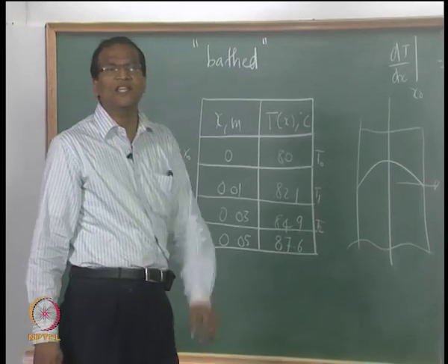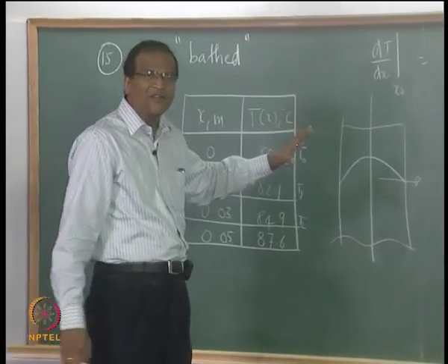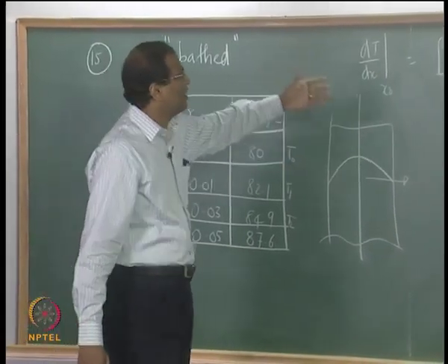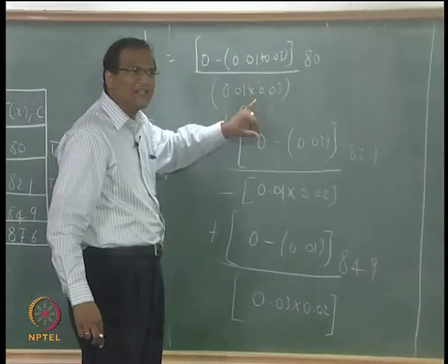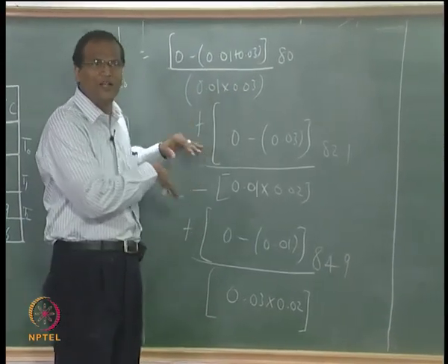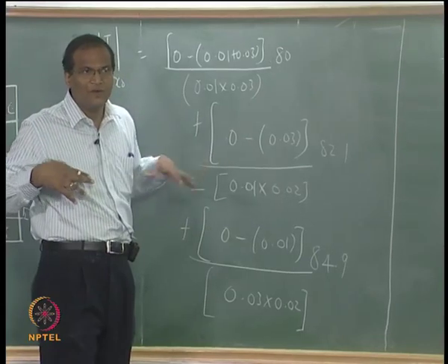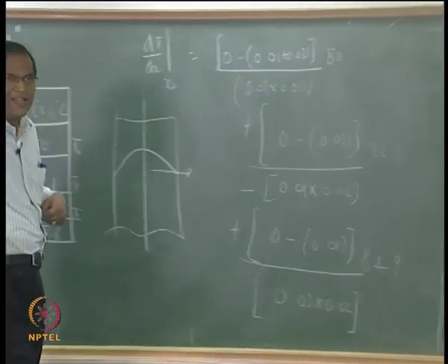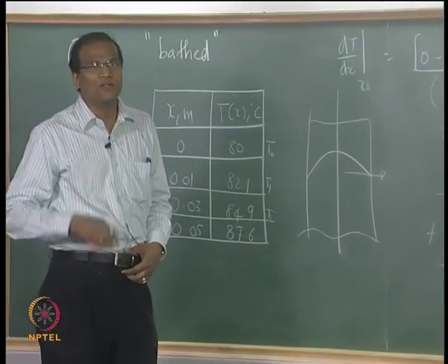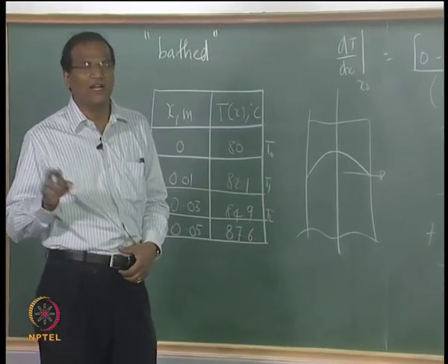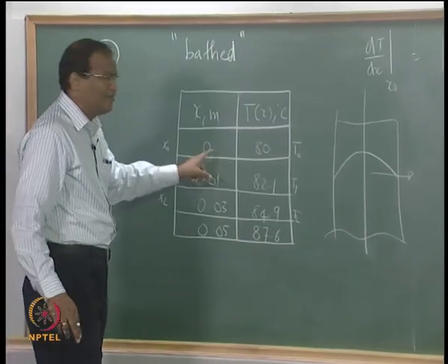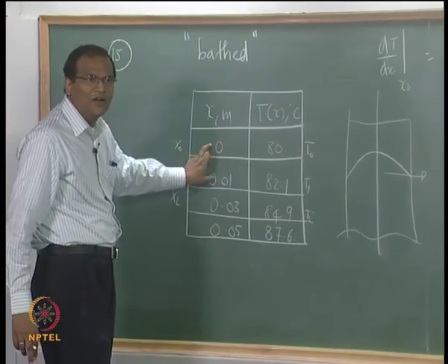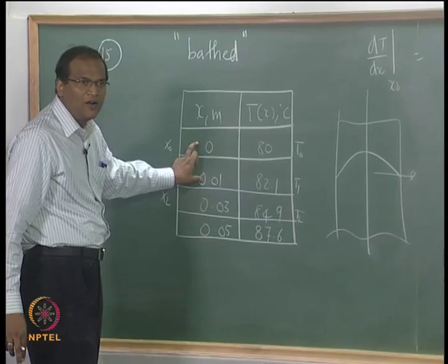You got 233.3. See, when you do all this complicated stuff, you are taking 0.01, 0.03, minus, plus and all this, and there is a possibility that you can get lost. But back to basics is very important. If you took a very desi approach, you will take only 2 temperatures and divide by delta x. So 2.1 divided by 0.1, what is the gradient? 210.